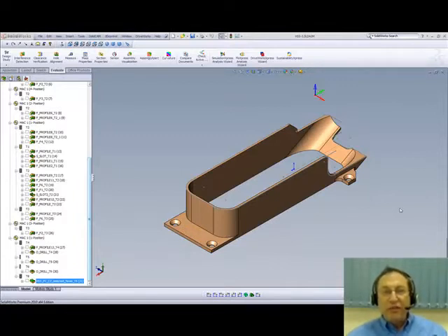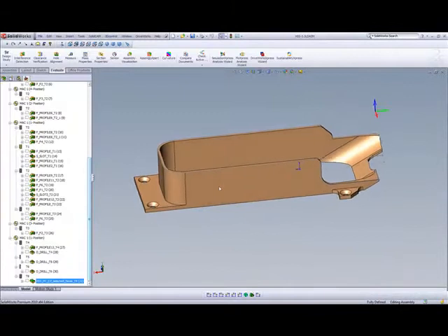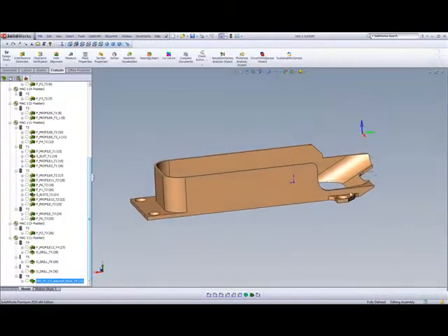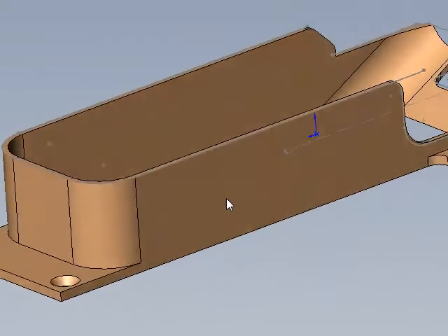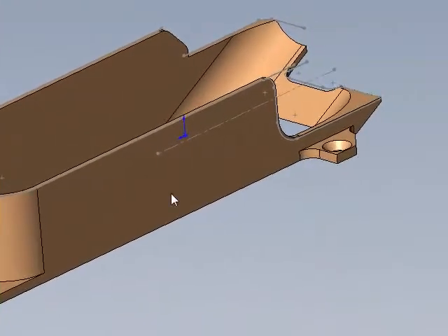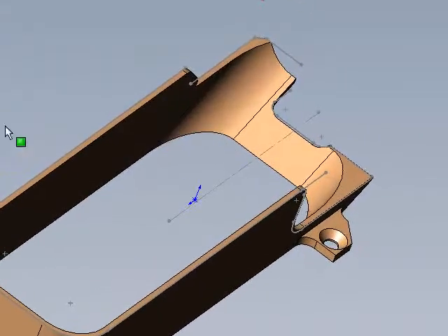I'm Sydney, your SolidCAM Professor, and in this session we'll be showing you another example of how HSS can be used on a typical 2.5D part where only certain operations must use HSS. If we take a look at this part, you can see this is a basic prismatic part where all the machining here can be done and has been done using 2.5D, except for this particular area over here, these surfaces over here.